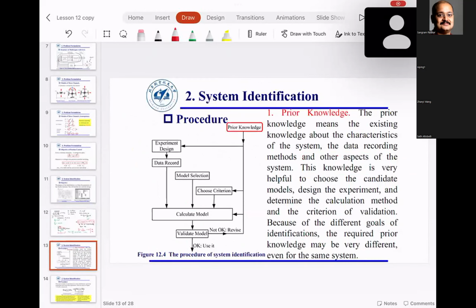Once you have this system model, you test it by performing repeated experiments under varying conditions. So, for example, you get the data by giving the system a step input and you capture the system dynamics. Then predict, if I change that step input to a ramp input, how would the system behave?